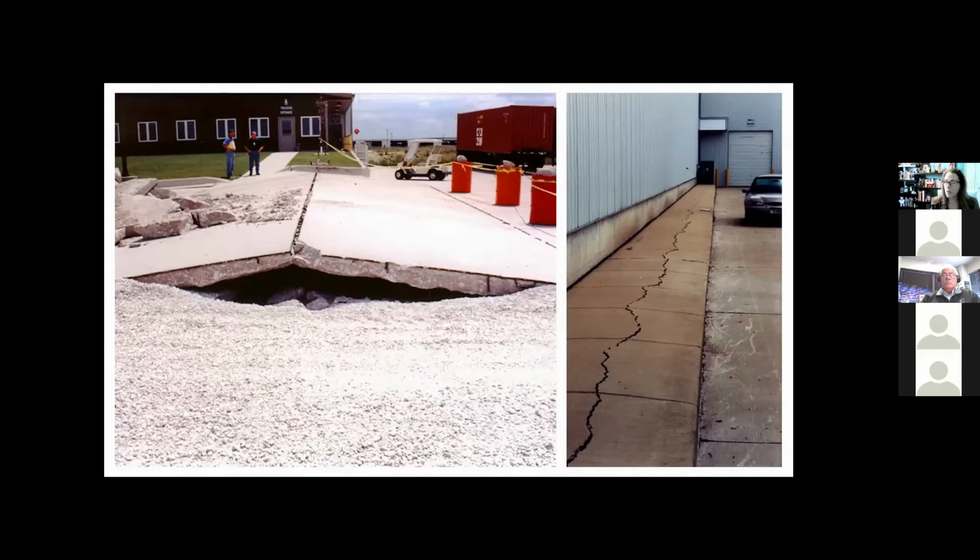And if it hadn't been there, most likely that building's foundation wall would have felt that stress, which would have been a much bigger structural issue. So we can thank that sidewalk for putting in an expansion joint. However, what we really should do is put an expansion joint against the sidewalk that is wide enough, and then potentially put another expansion joint every 50 or 100 feet, depending on how big this parking lot is, and then redo the sidewalk to give it another go.